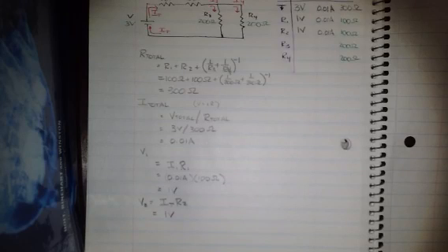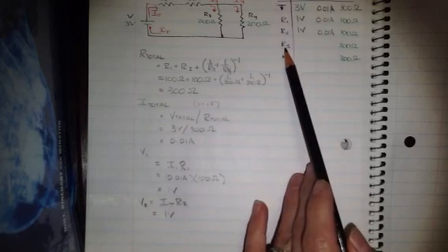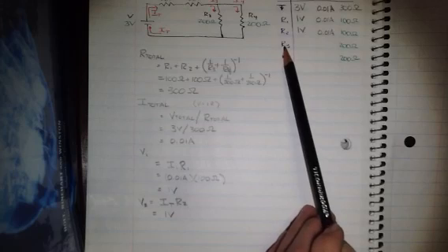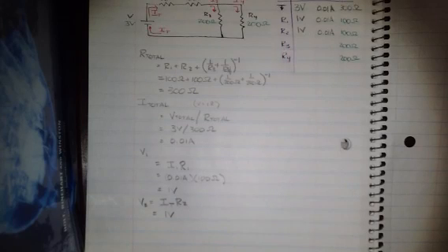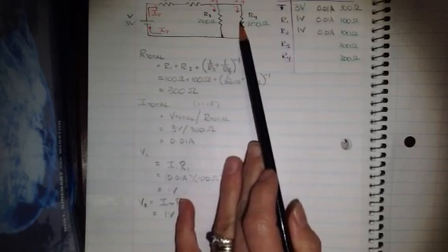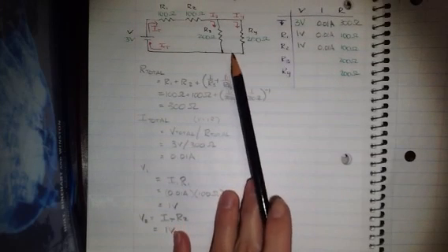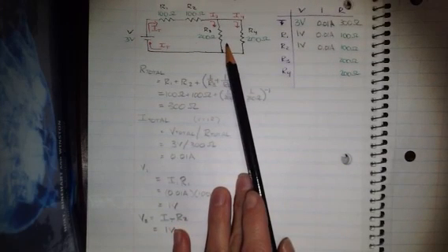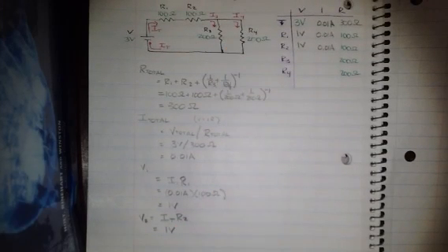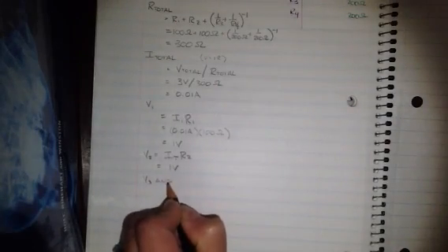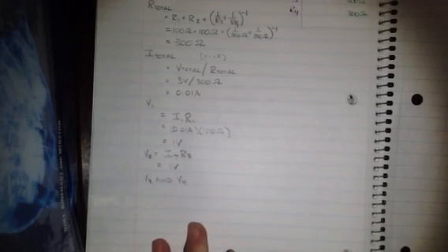Where you go from here is a bit a matter of preference. I'll keep working my way down. Let's find the voltage drop across R3 and R4. R3 and R4 are in parallel. The voltage drop across these guys is the remaining voltage left from the battery after it dropped across 1 and 2. Let me show you. Voltage 3 and voltage 4 are the same value.